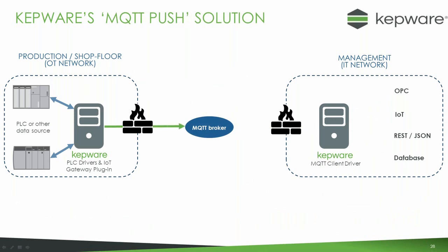You can also achieve a similar sort of thing using an MQTT broker. This can be an MQTT broker which is present on your network, that you would put onto a PC and put inside a DMZ, which is similar to the DMZ application we looked at before using OPC UA. Or this could be a commercial MQTT broker, perhaps on the internet. It makes no difference. The copy of KEPSERVER on the OT network will be getting data from the PLC drivers and pushing it to the MQTT broker.